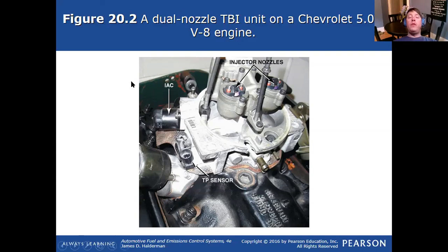So these throttle body or central fuel injection systems had fuel injectors that literally sat on the top in the airstream, like an airflow stream underneath the air filter, and they would pulse width on and off based on fuel load or fuel demand by that engine. So in the past, right there, this central fuel injection throttle body component was the carburetor. That's where the carburetor sat.